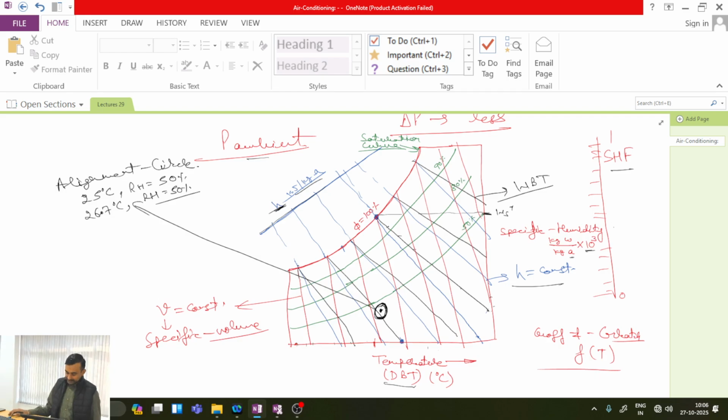Another interesting fact: relative humidity, specific humidity, and other parameters such as dew point temperature are actually difficult to determine directly. So for specifying the thermodynamic state of moist air, we require three properties: pressure, dry bulb temperature, and wet bulb temperature, which we can measure by putting a wet wick around the bulb of the thermometer.